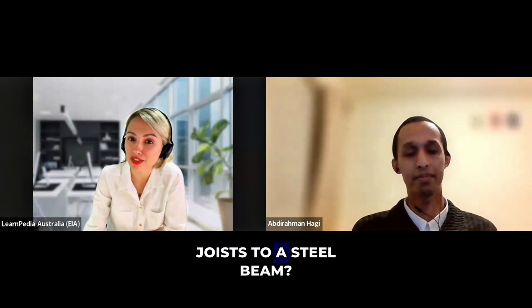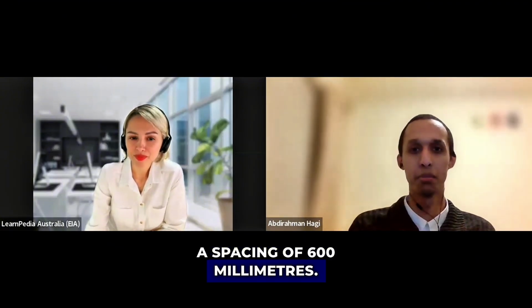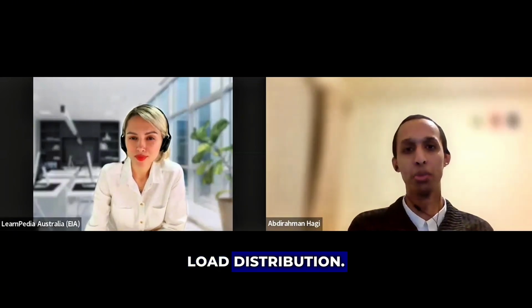Now, Hagi, the second question is, can you explain connection details for the first one, timber floor joist to a steel beam? So how do we connect a timber floor joist to a steel beam? Okay, to connect a timber floor joist to a steel beam, first you need to change the surface of the steel beam. And to do that, you can use a timber packer, which is fixed into the webbing of the steel beam. And the packer is bolted in a staggered pattern with a spacing of 600 millimeters. This is to ensure there's an even load distribution. And once the packer is secured, then you can use joist hangers to connect the timber floor joist to the timber packer.